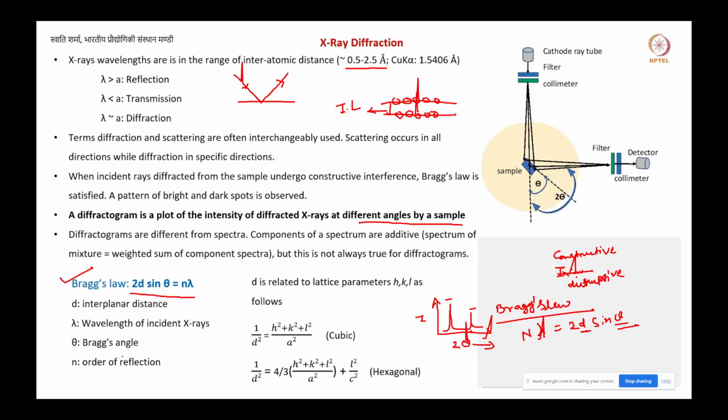reflection. So suppose you want to put in the value of d. This d is different for different crystal structures. Let's say you have cubic, triclinic, monoclinic, hexagonal, I mean, different crystal systems. For your material, lambda you will already know, since you know what wavelength you are using. Theta you will know, what angle it could be, and d depends on the material. This depends on the lattice parameters.